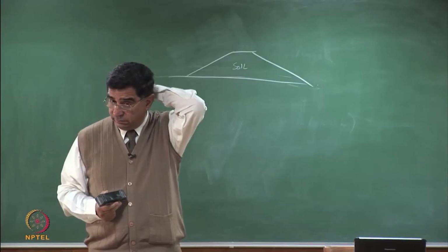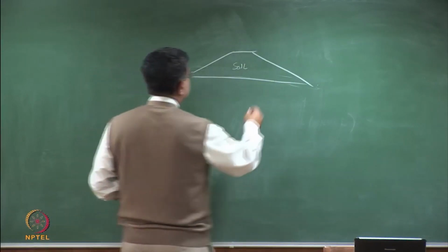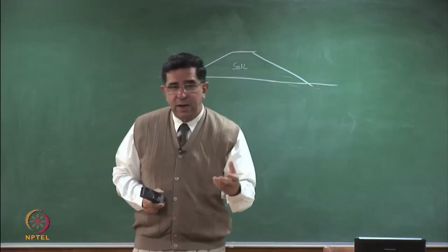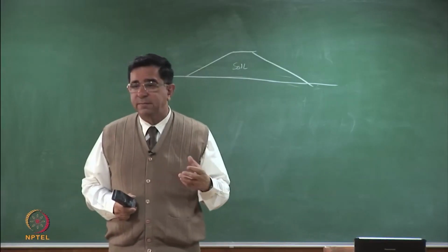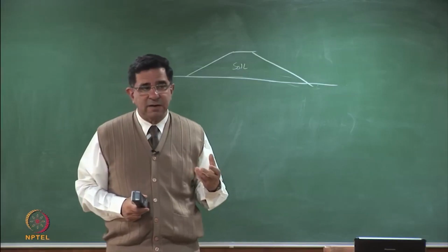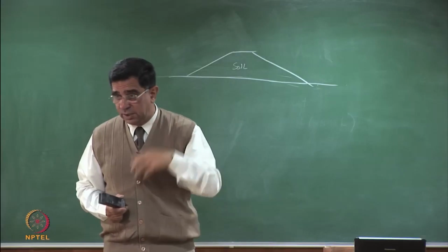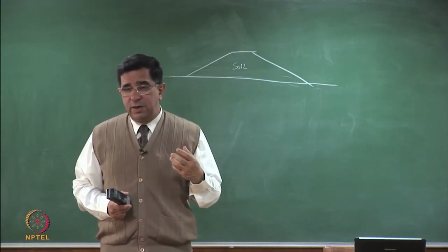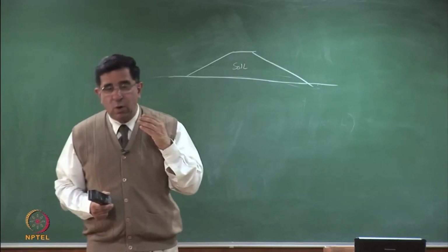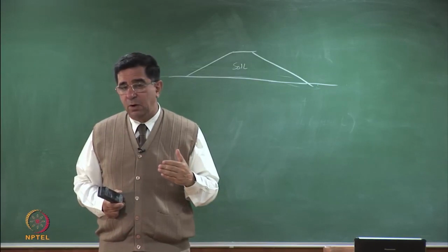If I have clay, how will I do the test? Again, I identify a borrow area, I bring the sample to the lab, I do the shear strength tests on as compacted samples. They can be as compacted, or they can also be as compacted then saturated when I am simulating seepage, if I am expecting any seepage. What tests will you do on clay in the laboratory?